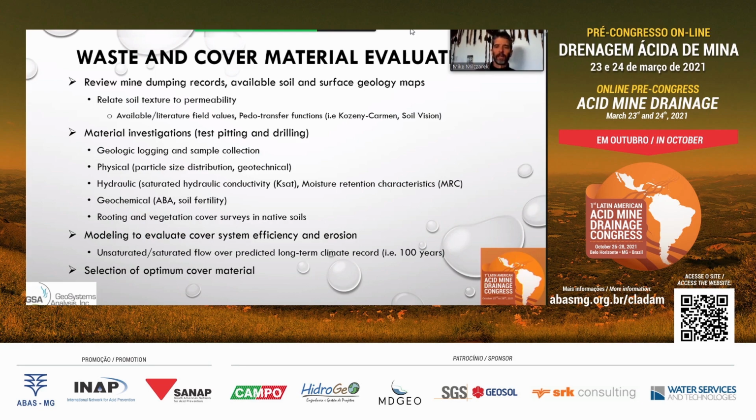And then that will help you with your initial design evaluation in terms of what you want to investigate, and going out and test pitting, drilling stockpiles, for example, and then actually collecting the samples and doing a very good, very careful job in terms of looking at what the materials are, what the physical properties are, hydraulic properties, geochemical.